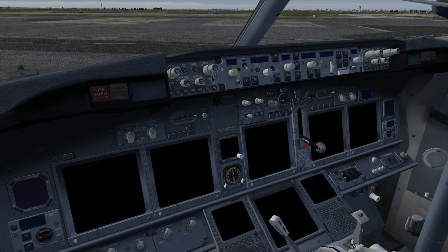Those 6 screens are off now, and they present the data that is calculated by aircraft systems or equipment. The data for these screens is collected by a system called the Air Data Inertial Reference System, or ADIRS, and this system is composed of different equipment. We have 2 units called Air Data Inertial Reference Units, or ADIRU. We have ADIRU left and ADIRU right, or 1 and 2.